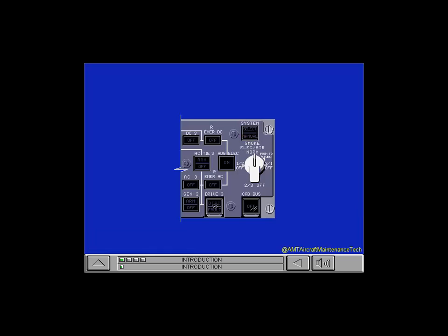If you push the generator 3 switch when the ESCP is in the automatic mode, the manual light on the system switch flashes. The manual light will continue to flash until you release the generator switch light. The electrical system uses the system switch light to tell you that it cannot do that task in the automatic mode. When you release the generator switch light, the manual light on the system switch will not flash. The system stays in the automatic mode.